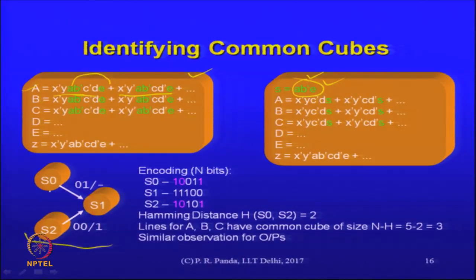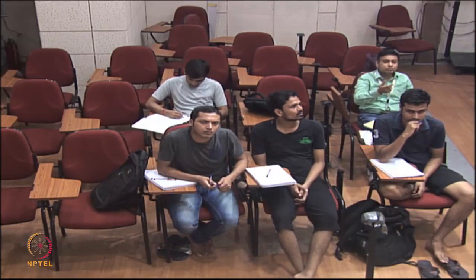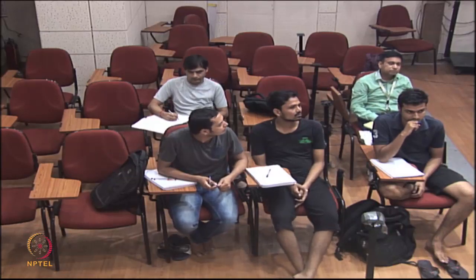Yes. Typically, when we code an FSM, even while writing RTL, it is advised to keep the states as enums, so that your RTL is readable. Yes, right. So that means encoding is even done at gate level synthesis, where the RTL to encoding part is part of a more general problem.